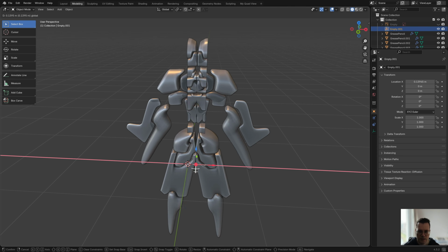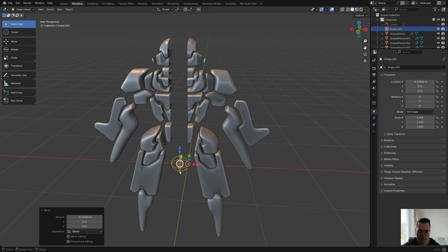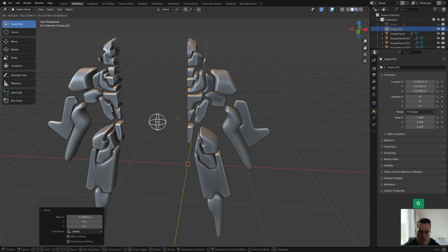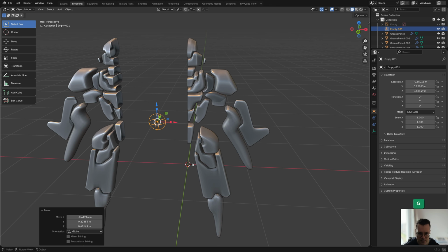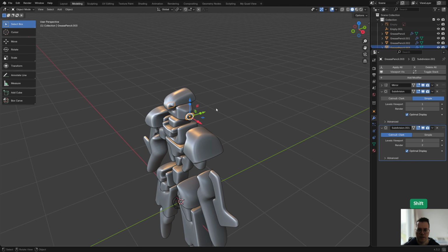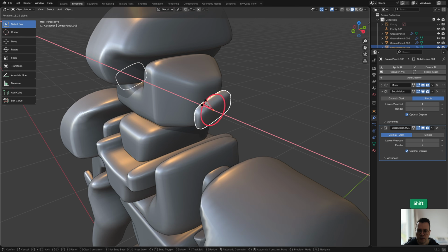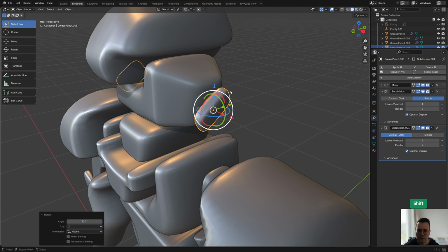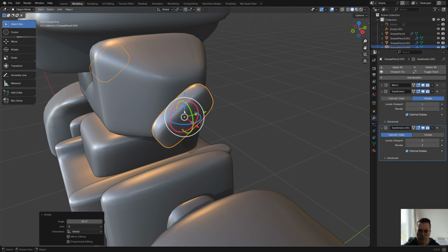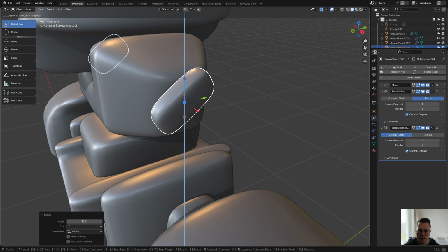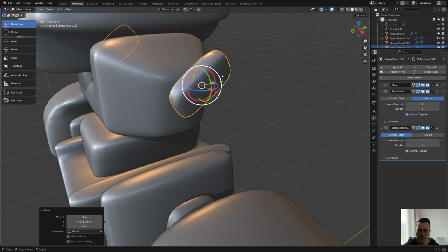And yeah, this kind of controls where it mirrors from. So it's best to just leave that in the right location. If you accidentally move it and you don't know how to put it back here in the center, just select it and press Alt G. And so now I have the origin here in the middle. And let me just turn on the rotate gizmo as well. And so now I can use these circles to rotate this. And as you can see, I also still have the scale gizmo and the move gizmo. So I can use that to adjust this.